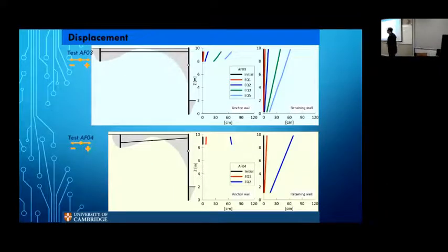If you look from the camera itself, you look at where the walls have gone. The front wall, in this case, after each earthquake is moving horizontally and also rotating. And we can also track what the back wall, the anchor wall, is doing at the back. And you can see that thing is rotating. That's because we attached it at the top third position.